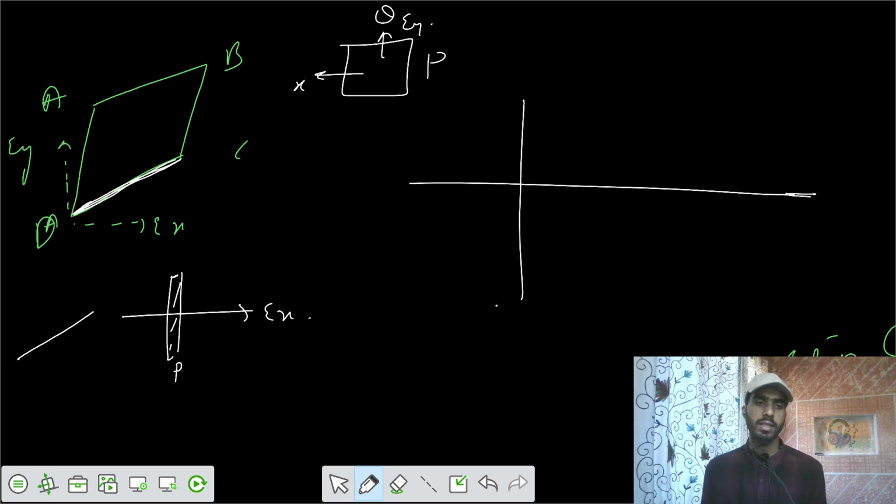Along plane P you have strain in X, and your shear strain is this part, along the x-axis. This is making an angle of theta, anti-clockwise, so theta is negative. We can say gamma xy is negative. So the coordinates would be epsilon x comma minus gamma xy, divided by 2, because we are talking about one half on a particular plane. There is only half of that gamma shearing strain.